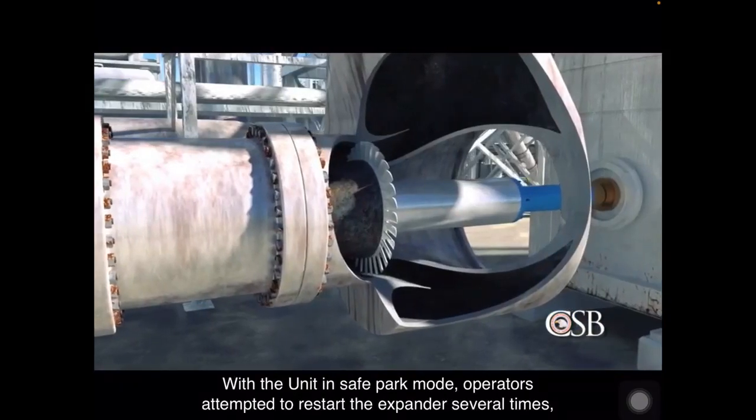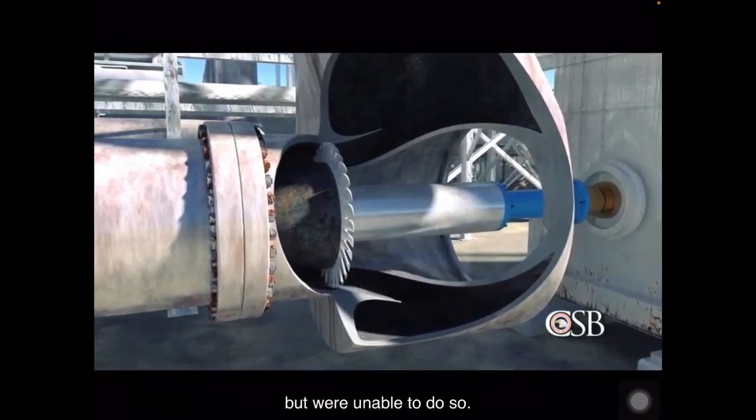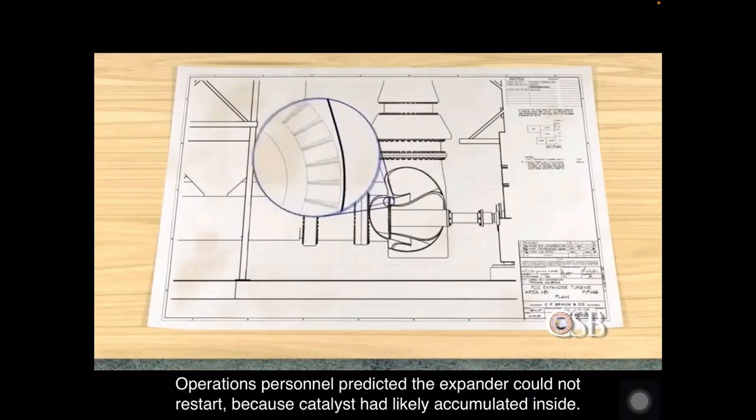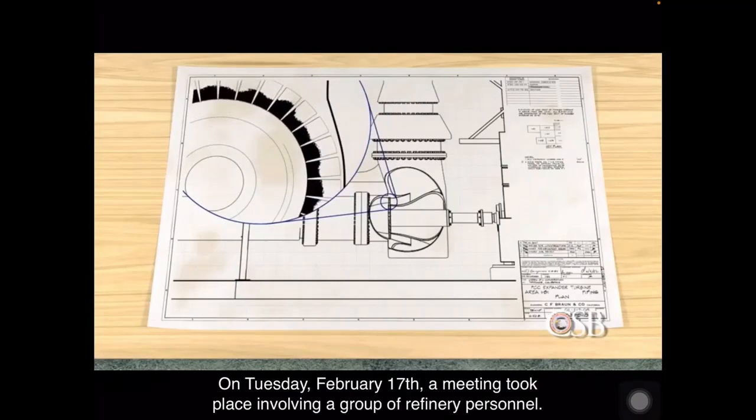With the unit in Safe Park mode, operators attempted to restart the expander several times, but were unable to do so. Refinery personnel met to identify a strategy to repair the expander and bring the FCC unit back online. Operations personnel predicted the expander could not restart because catalyst had likely accumulated inside. On Tuesday, February 17th, a meeting took place involving a group of refinery personnel.